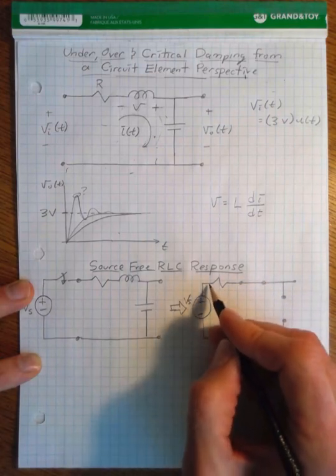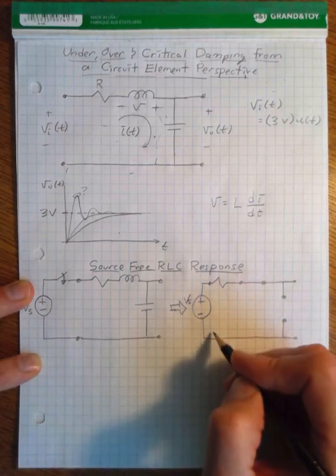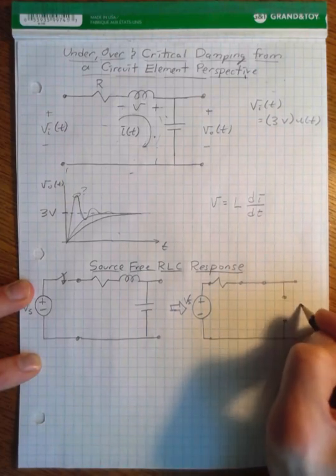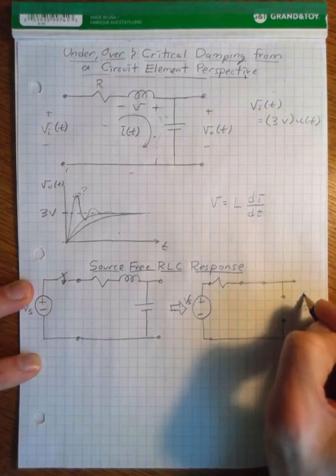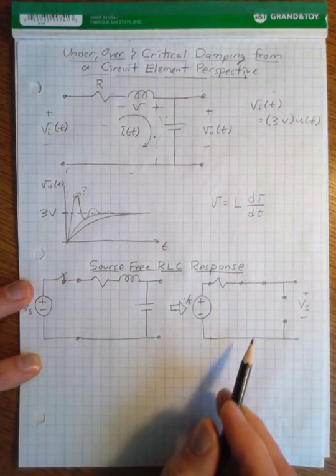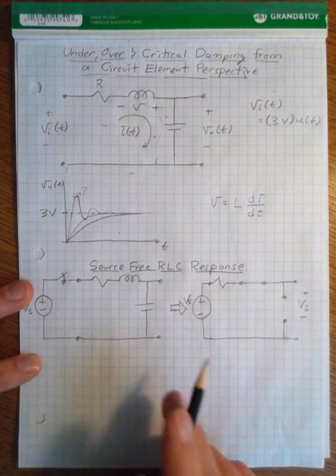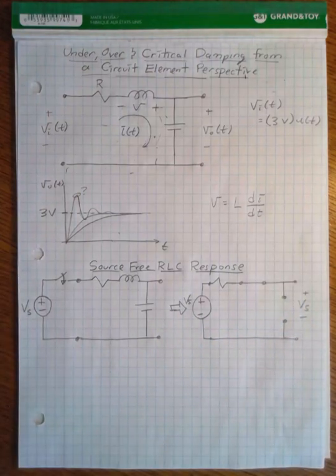And so if the voltage at these 2 points is equal to Vs, then the voltage at these 2 points is going to be equal to Vs as well. Therefore the steady state response of our circuit is just equal to our source voltage. And we know that, right? We saw that in the previous step response module because everything was converging to the 3 volt level.